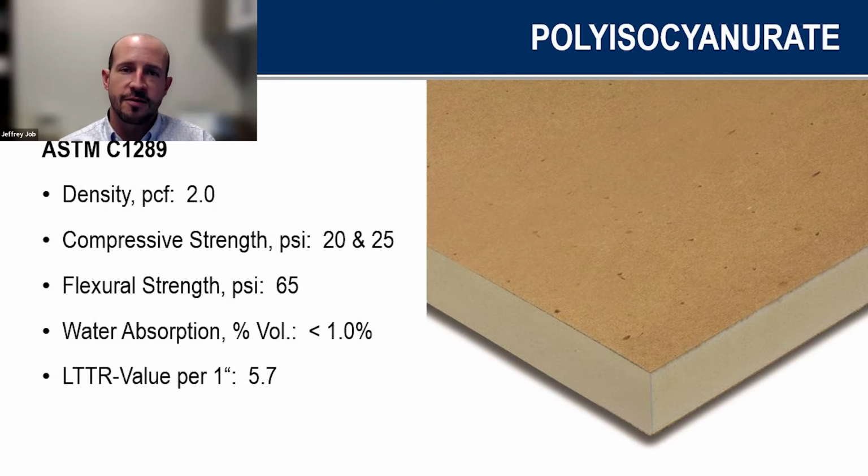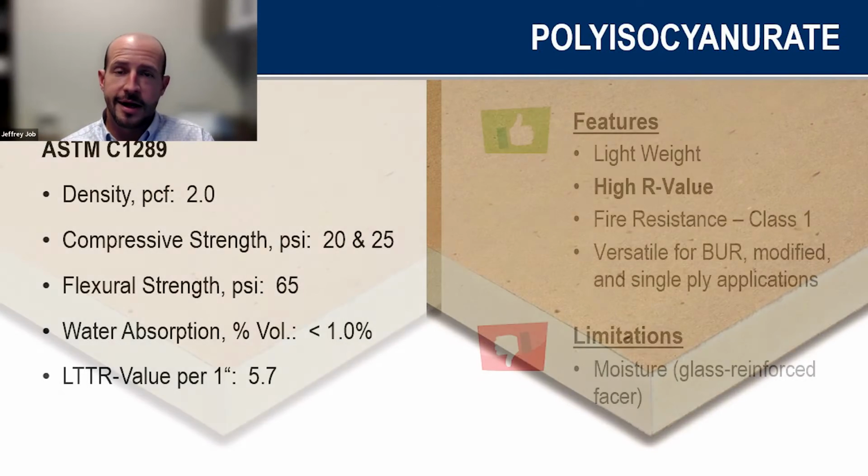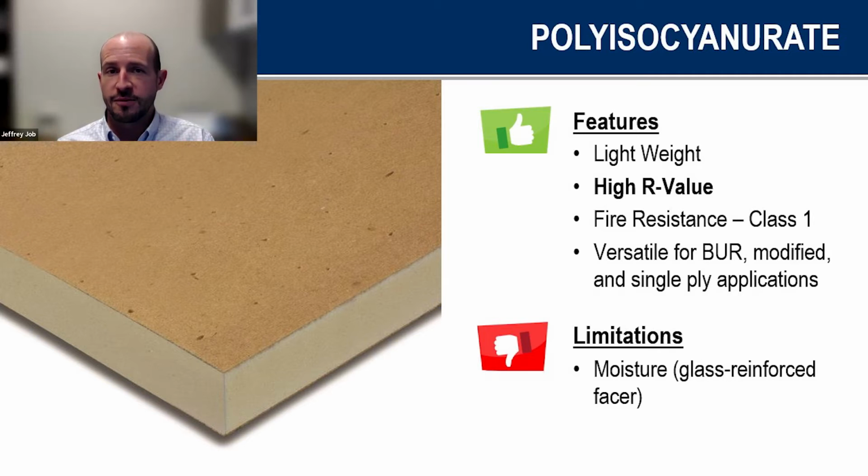A couple other benefits of polyiso versus polystyrene. As I mentioned already, polyiso is a thermoset material versus polystyrene being a thermoplastic. So when we get into fire performance, that does have a significant difference. The polyiso will char versus melting away like a polystyrene. So from that perspective, thinking of approvals and fire performance overall, polyiso does seem to shine above the styrene products. Again, just some of the additional benefits there on the ISO side of the styrene products.